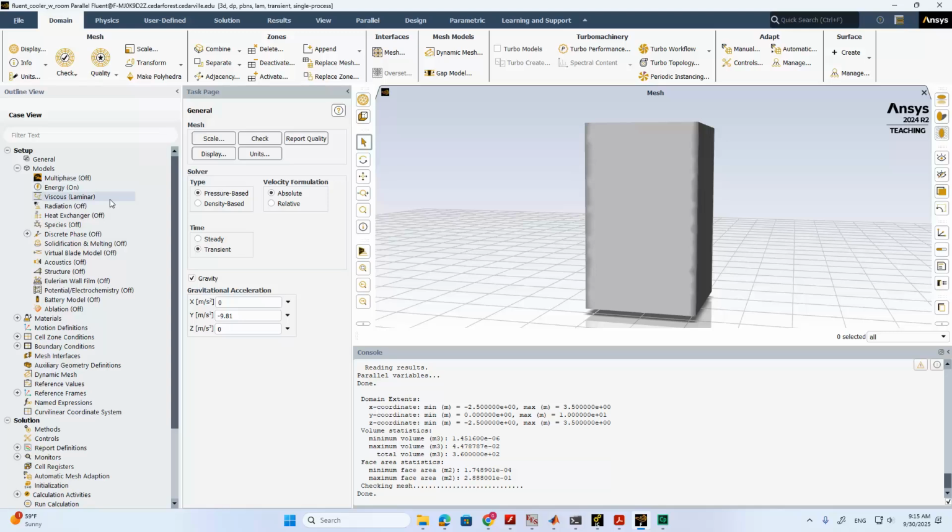It really depends on the so-called Rayleigh number, Ra. Just check your heat transfer textbook or simply Google this number, and find out how to calculate the Rayleigh number and find out the criteria for the natural convection to become turbulent.